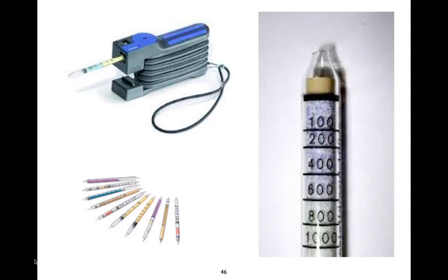One of the ways that we estimate the amount of exchange with outside air is by measuring the carbon dioxide levels inside the building. The idea, and you saw that referenced briefly in one of those ASHRAE standards, is that if outside air has 350 or 400 parts per million of carbon dioxide, and you go inside and measure it indoors and it's higher than that, how do you account for why it's high? Why would it be higher indoors than outside? Somebody want to give me an answer to that quick question?